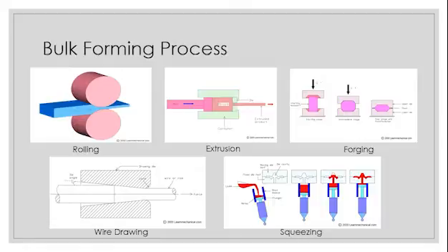The next process is extrusion. The extrusion process is much different from other processes. In this process, the metal is heated at high temperature, then the metal is pressed by the compressive force of the die. The die has an opening through which the heated metal flows at the time of pressing by a ram. Hence, the proper shape can be made. Apart from that, in the extrusion process, the metal is heated so much that it becomes like a fluid and it can flow.